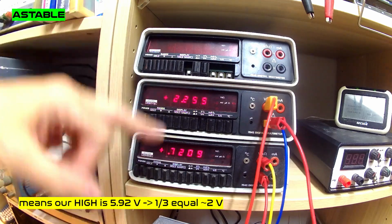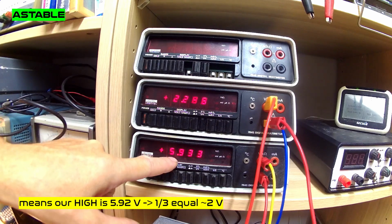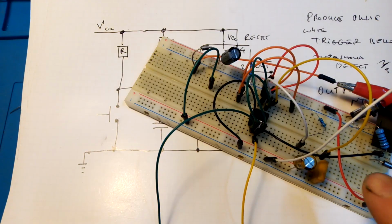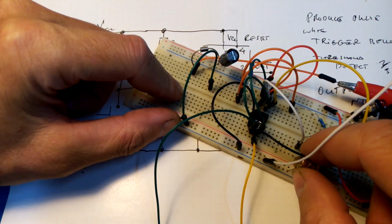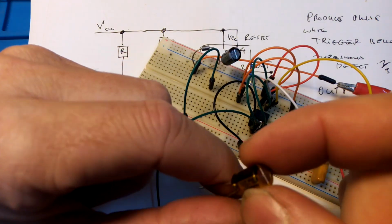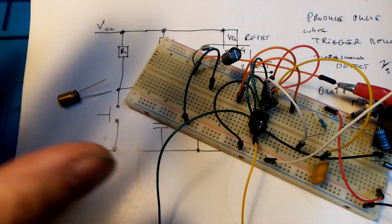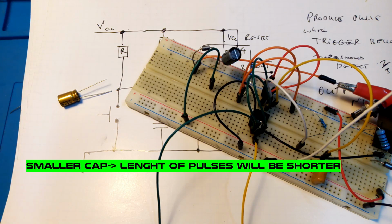It means the output will be high again, and the LED lights. As we will see, this depends on this external capacitor. Right now we have 100 here. So let's change it for something smaller. Of course you have to check it in the calculator, but we just replace it with a smaller one and we will see what happens.